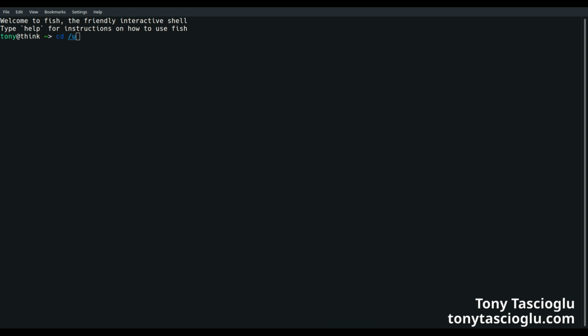Fortunately, we don't have to come up with all of the configuration options by hand, as we can figure out which parameters exist by checking the header file for the microcontroller we are using. The easiest way to do this is to hop on over to the SDCC directory, which is at /usr/share/sdcc. Here you will see three main folders: include, lib, and non-free. The IC we are using, the PIC18F2550, is under the non-free folder. This is because while the source code is distributed, the license that Microchip has unfortunately put over their code means that it cannot be distributed everywhere.